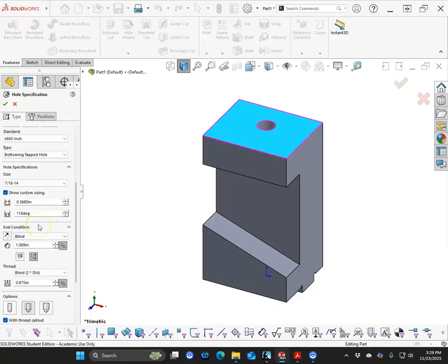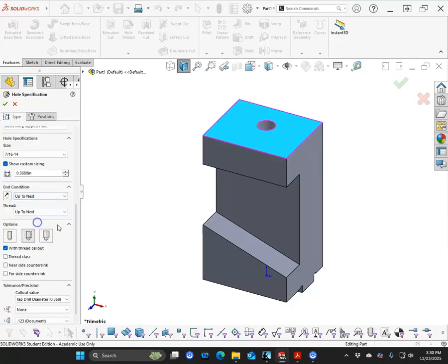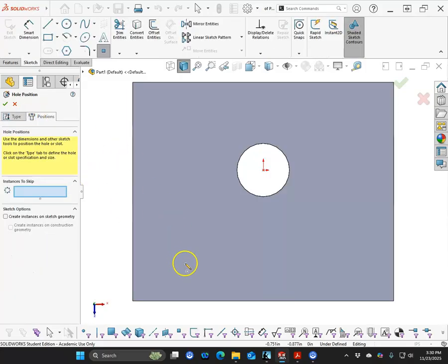And I would say from a machining standpoint, I don't run into 7/16-14 that often. They do show up, but chances are 3/8 is going to be something we use more often. I don't know that there's a strength issue here for holding down whatever tool post or adjuster that they're doing. So we do want to go up to the next, because the through wall would find its way through the bottom of the part.